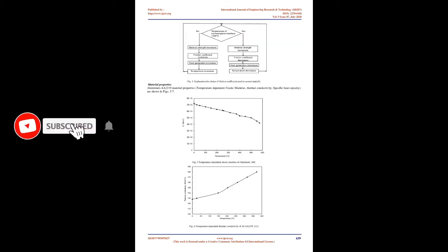1. As mentioned earlier, no heat flux acts as a heat source in the present work. On the other hand, heat generation in the model was due to friction and plastic deformation at the interface of the Pintool and the workpiece. Where σ is the yield stress, ε is the equivalent plastic strain, ε̇ is the effective plastic strain rate, and ε̇0 is the normalizing strain rate. Here, A, B, C, n, and m are material/test constants, and Tm and T0 are the melting and reference temperatures, respectively. Material properties of the AA2219 used for the Johnson-Cook model in the current study are listed in Table 1.